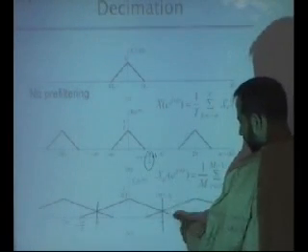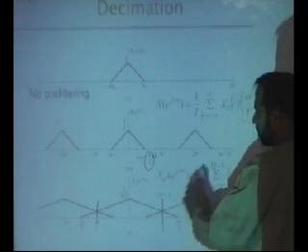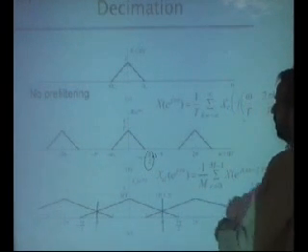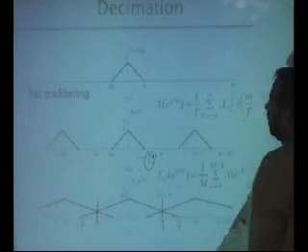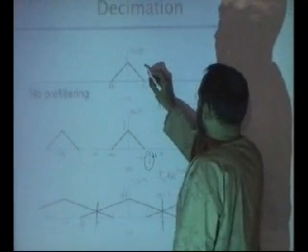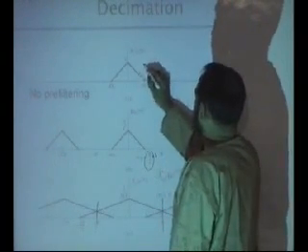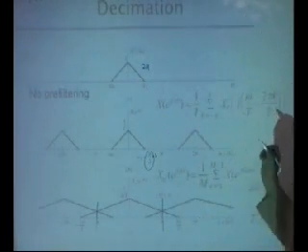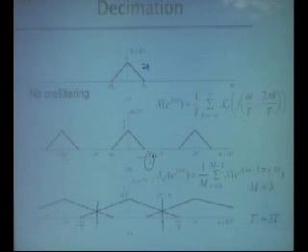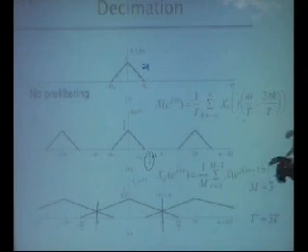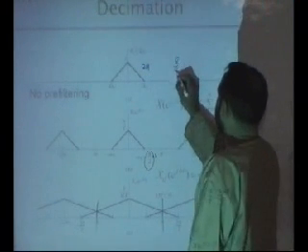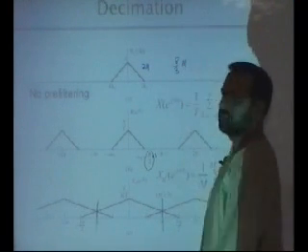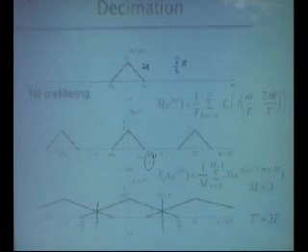But this is the example of aliasing, and this is true even if you start from here and say, instead of 4, let's say 2 mega, and instead of sampling it at 4 mega, you first sample it at 8 megahertz, and then instead of dividing by 4, you divide it by 3, so 8 by 3, which is 2 point something.